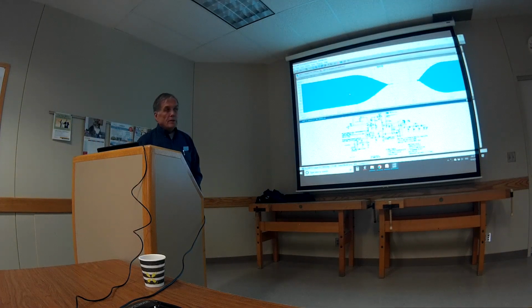Here's the output. Obviously this time frame is not what you'd really have. Even at 20 words a minute, a dit is going to be 60 milliseconds, so this one will only be 3 milliseconds. But this is showing you the keying. It's not a sharp cutoff or rise, which you don't want. You want that slope in there. That's why all this extra circuitry is here, to make it slope off with the capacitors charging everything.